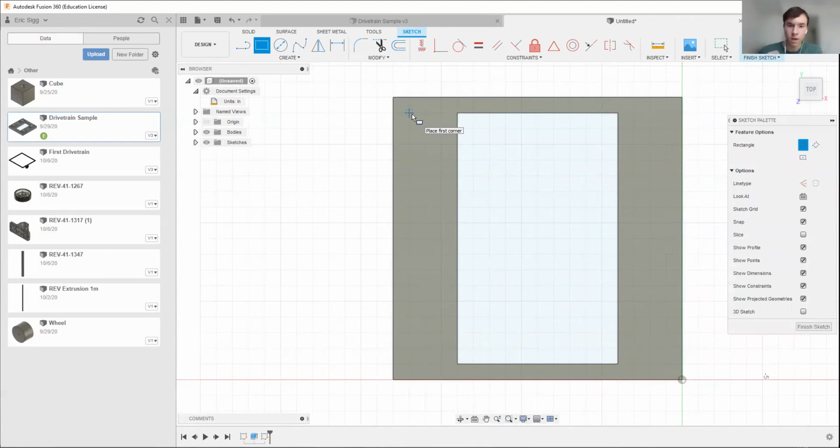Now, FTC wheels generally are about 1 to 2 inches thick, and they're usually about 4 inches in diameter. So we want our wheel wells to be slightly larger than the wheels such that they will fit very easily. So we want our wheel wells probably to be 3 inches wide, and about 5 inches long such that the wheels will easily fit inside. Now, we want this to be 3 by 5, but it's obviously not centered again.